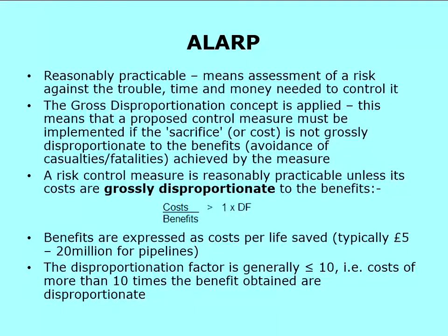Right, so we'll look at the principles of the UK pipeline legislation, which again, these are fairly broad principles, so if you looked at legislation in other parts of the world, you would see parallels. Basically, the key principles are, there's general duties which apply to all pipelines, and that means you've got to design, construct, operate, maintain and decommission them. You've got to do it properly, you've got to do it according to the codes. And then the additional duties for major accident hazard pipelines, which could cause major accidents if they fail.